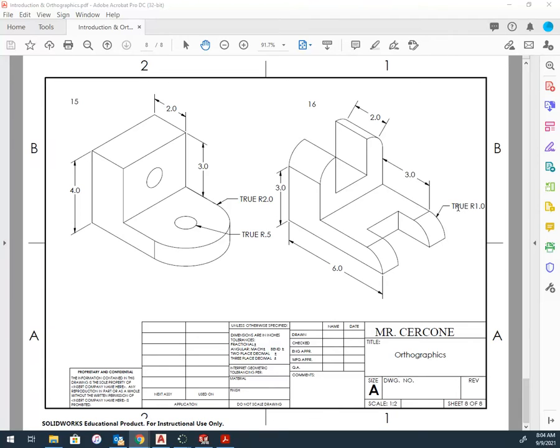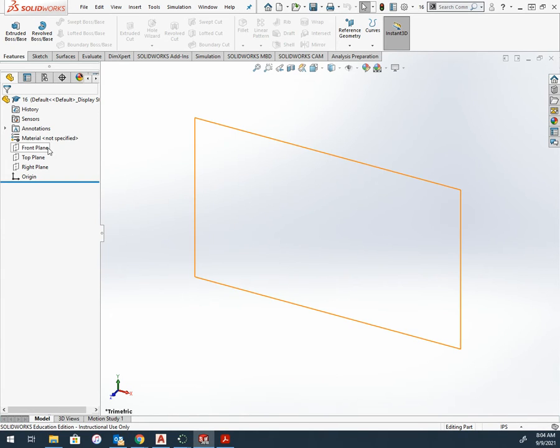I'm designing number 16. When I see this, I forgot to mention here and here it's a 2x2. These fillets are all a radius of 1. When I extrude this, if I extrude from the mid plane, it will make centering these rectangular cuts a little bit easier. So drawing from the front,